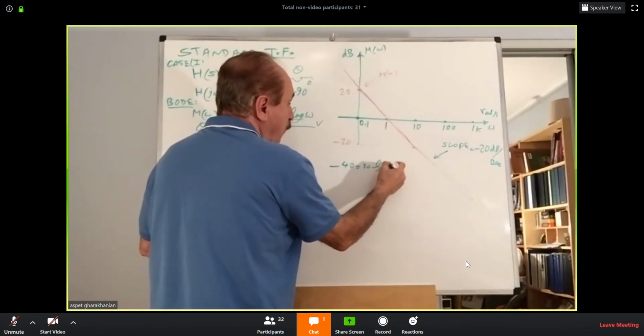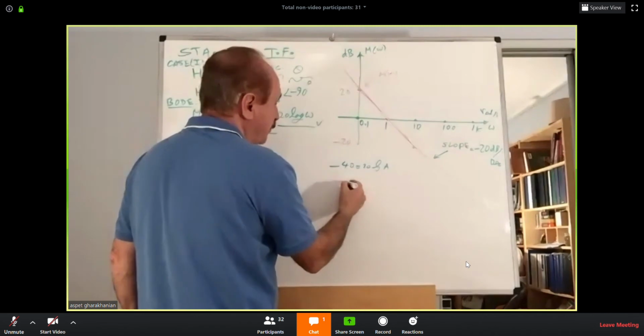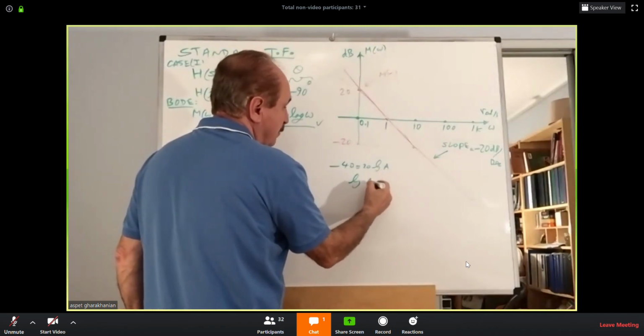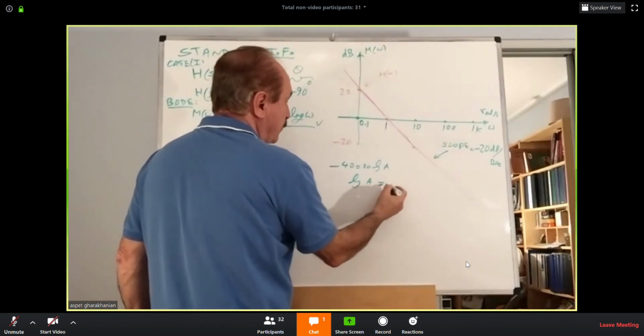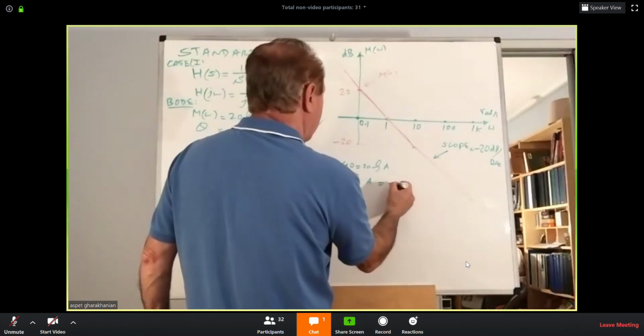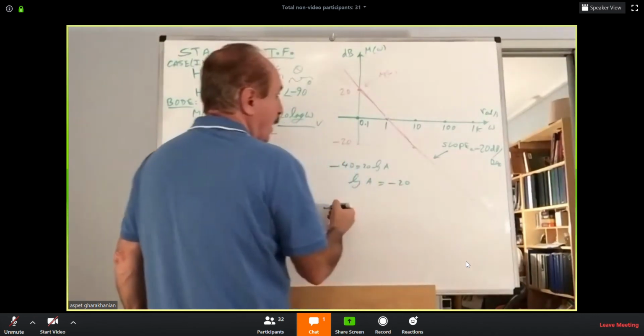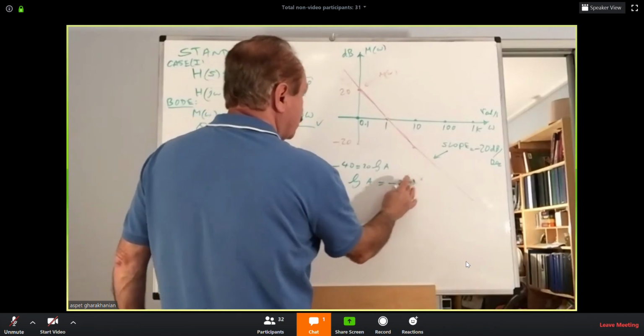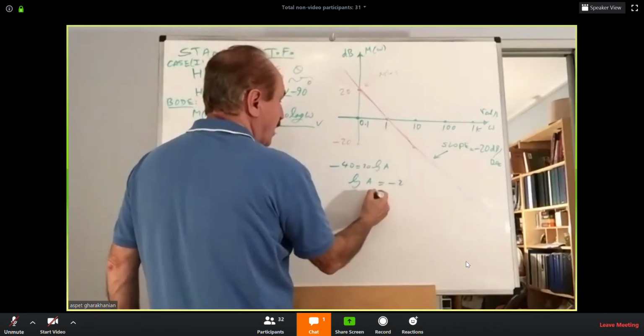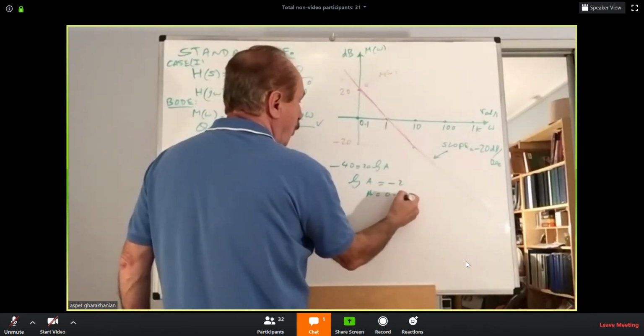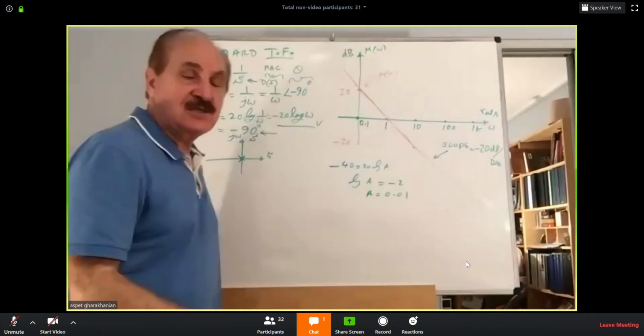Minus 40 dB means minus 40 is 20 log of what? If you calculate, the log of that number will be equal to minus 2. And that means A has got to be 0.01.